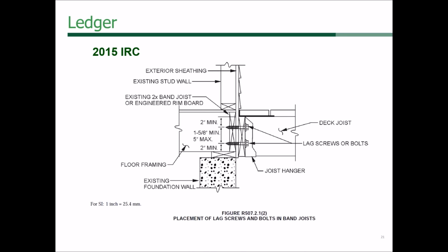So this is a tested application. They mocked it up in the lab and they tested it to say, okay, this is the type of spacing and things we need for these lag bolts or bolts in general to make it work. So when using DCA6, you don't have to take the wet service factor, for example, because it's tested, it already accounts for it. But if you're trying to do design, you're going to need to do that.